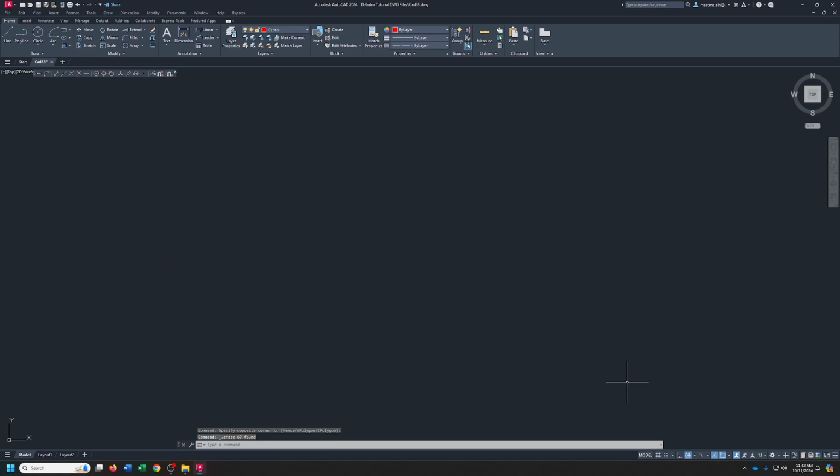All right, so since everybody likes to draw the side view as the front view, we'll do the side view first, and it's pretty simple. It's all diameters, okay? So once again, make sure you're on the object layer. We've got a diameter of 3 and a diameter of 4, so we'll do the 3 first, and then we'll do the 4.